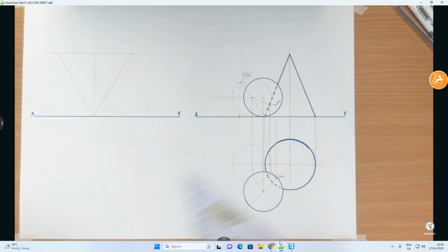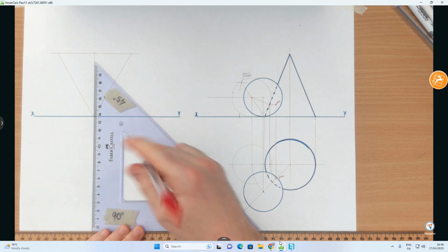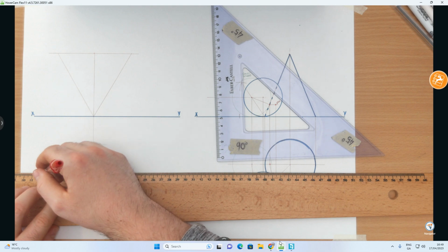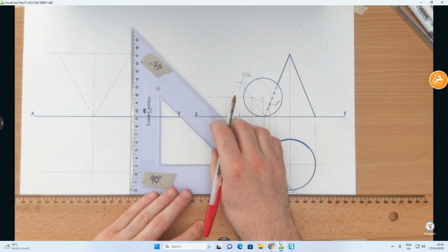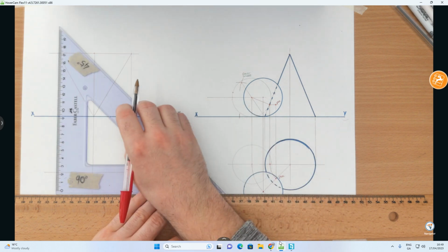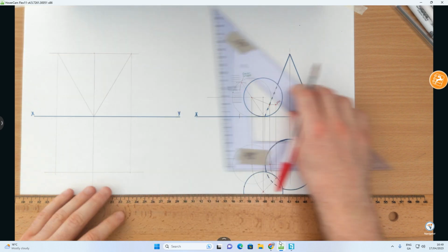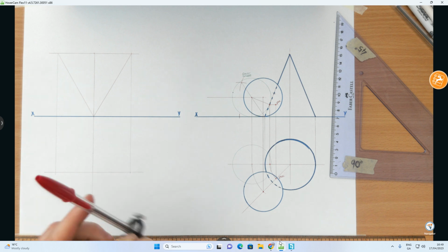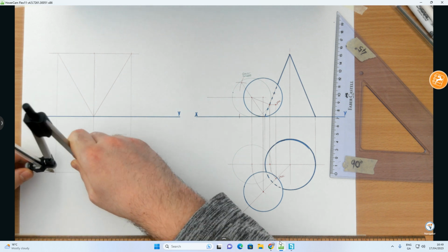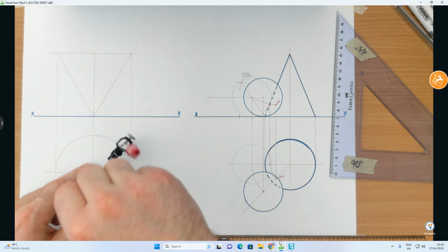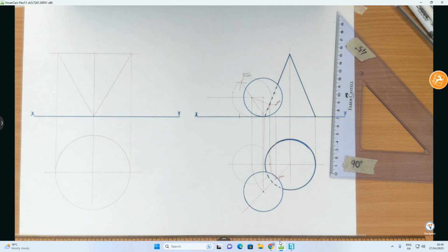We now have to find the cone in plan. Likewise with the center of the circle in plan, as we would see it, right down, line out like this. Top point, bring this down as well, should work. And now draw in my circle, because that's what the sphere, or sorry, not the sphere, the cone is going to look like in the plan view. In this case, we're seeing the base of it as it has been inverted. So there it is. Okay, that's the first part of the question.